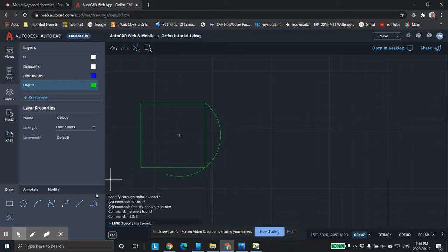The line tool is what we'll use most often, and the line tool is just that. You just draw straight lines. And the nice thing about it, so I anchored that one, and you can see the 60, or the 59, that's the length. So I could type in 55, tab, and then it says, okay, you want a 55 millimeter long line.